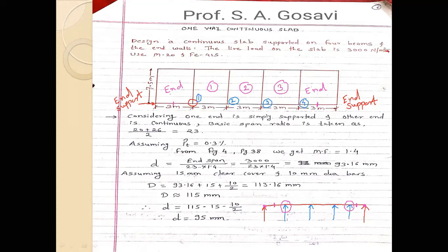And if you see the profile of the bending moment diagram, it will be something of this sort. Here the sagging will be there from this point to this point. Again some bending moment will be there at this point. This is the diagram. Again for this span, it is again sagging bending moment. Again hogging bending moment at the support. Again it will sag. Again here somewhere hogging bending moment. Again for this span, sagging, hogging, then again sagging, and it will come to 0.